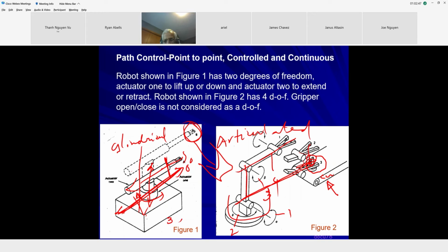That's this machine. Now, the 3 degrees of freedom being controlled could be done with a PLC, right? Because there is no path control. Substitute this machine for the same application. Where is the home position? Let's say the home position is what is shown in the figure. So when the part arrives, it doesn't have to rotate the base, but it has the ability to rotate this. That means this will fold down, then this will fold up to go into this position. From position 1, it goes to position 2 above the part.